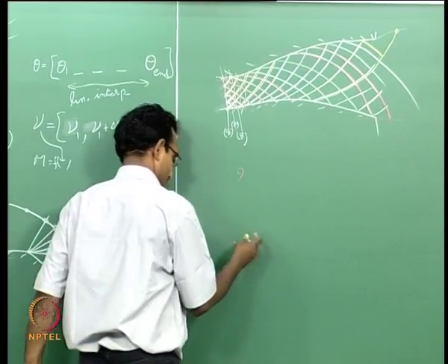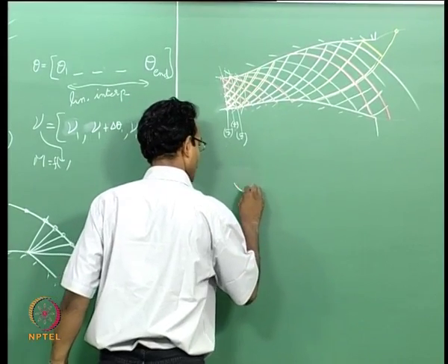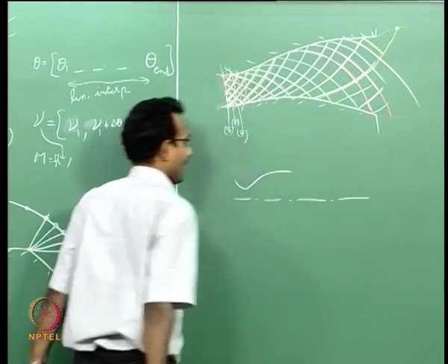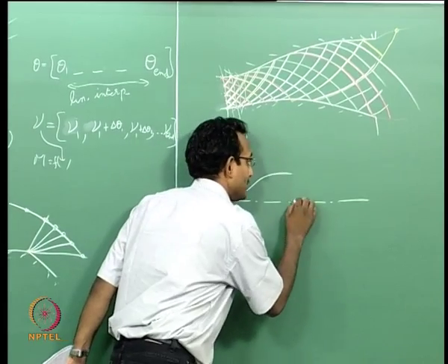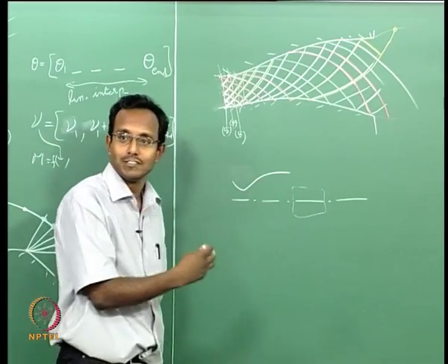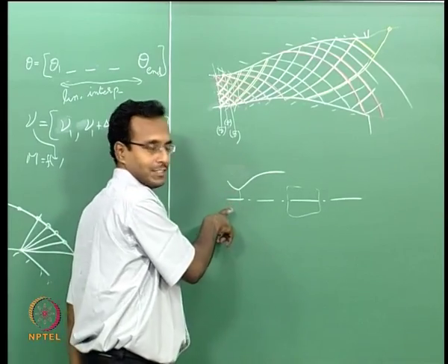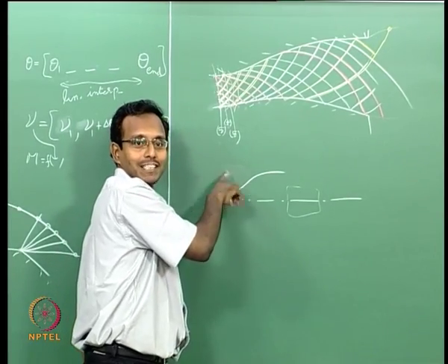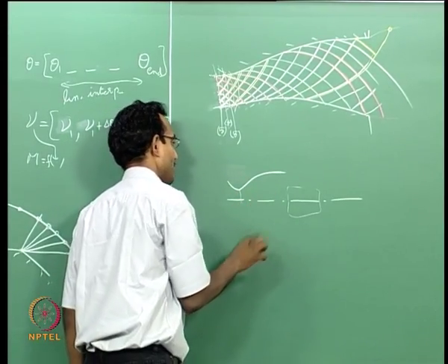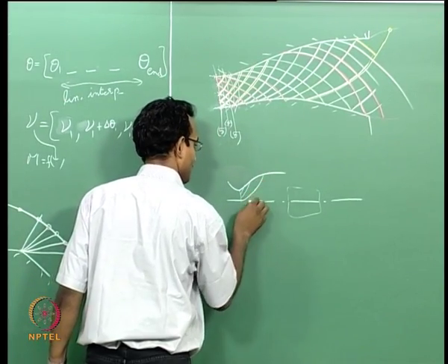For example, if I have a nozzle flow, and I am interested in the flow only in this small region in the center, and I want to solve for method of characteristics based method, somehow I started with some initial set of lines, and I am going to solve only top half. It is a symmetric problem, so I will solve only the top half. It is a 2D symmetric problem. So from here I can solve like this.